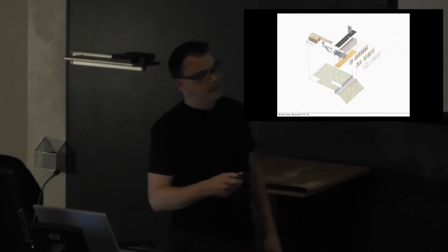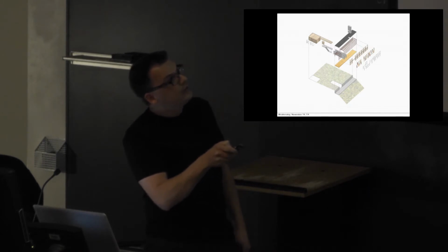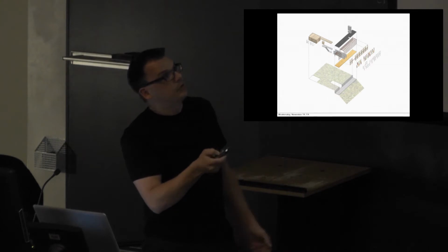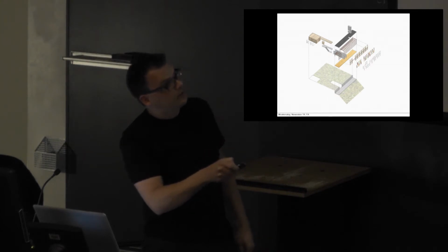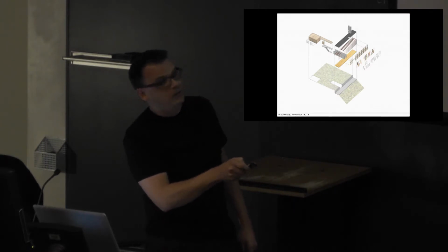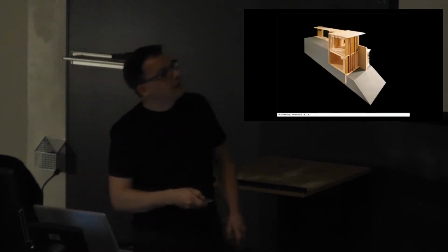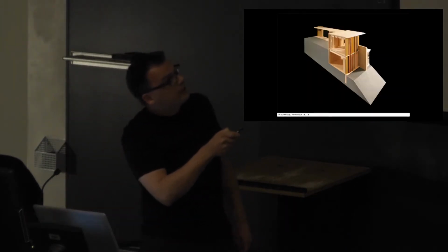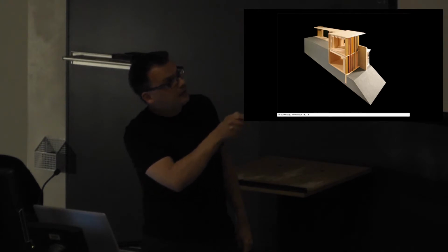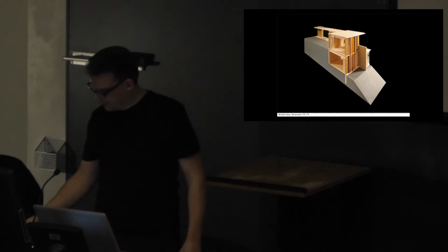Axonometric drawing showing the main building components, including the layered facade components here. The building is a simple post and beam structure that sits on a concrete shelf. This is the concrete shelf carved into the hill with a long retaining wall that you will see in a moment in one of the images that follows. The section model here shows the relationship of that plateau, the higher part of the site, and then the building carved into the bluff, with a drop towards the lake right there.